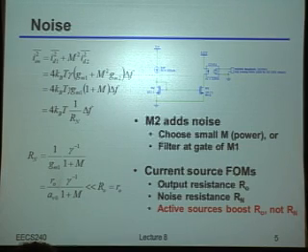Okay? So it should hopefully be pretty clear that if I just took the one transistor that I had as my current source and measured its output noise, that's a pretty easy thing to figure out, right? That's just 4kTγ times gm in terms of the noise current, right? But because we're using these current mirrors, we have to be a little bit careful about things,